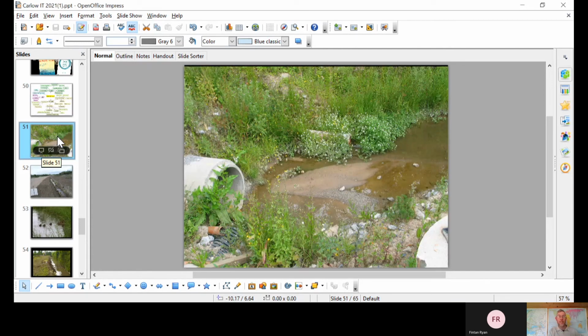So for sustained urban drainage systems, for runoff that comes from paved surfaces, from hard surfaces, so say a new housing estate, for example, a number of things happen. The volume of overall water increases, the volume of runoff in a peak event increases, the pollution load increases, and the storm intensity frequency increases. So if we can simply stop our pipes at the earliest opportunity and have an open drain, this is the head of an open drain that flows on down towards a stormwater wetland. As soon as we get the water out of the pipes, it begins to settle. So that's a clue as to how we start to treat it.